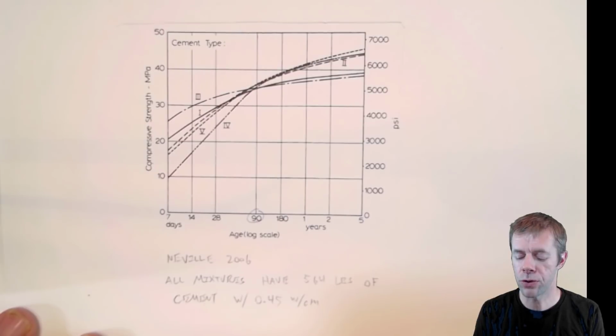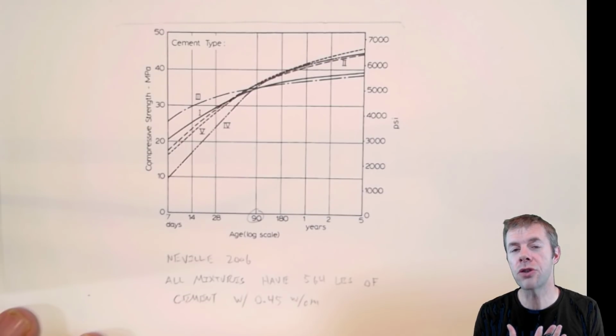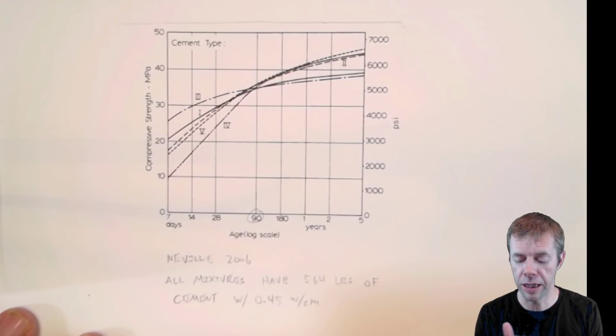Usually our specifications ask for strengths at like 28 days. And actually our contractors today want our strengths as fast as possible, within 3 days or 7 days, because they want to get the forms off, or they want to move on top of that concrete to use it for something else. So early age strength has been a huge focus for modern construction techniques.